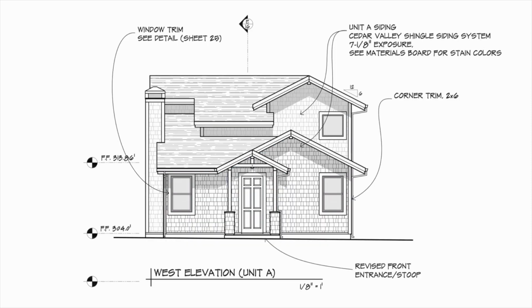Then we went to the little bit more technical drawing. Again, this is still design review, so we're moving forward. The first one was about color, general shape of the building, what does it look like. This one has a little bit more detail, a lot of emphasis on line weights. So even the shingle siding pattern, there's a thicker set that's closer to us, a thinner set that's further away. There's a little bit of shadow in there, and the thicker lines going around the building, etc. So whatever's closest to us is getting the thicker line weights. So this is, again, a design drawing. We're trying to sell, this is what we want to build.